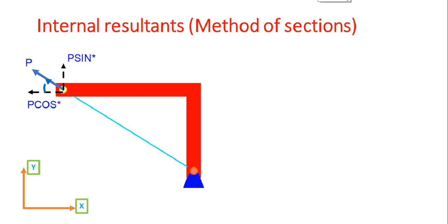Now, a pin joint can resist movement, so the first thing to investigate is whether the applied loading produces movement at the end point or not. From our previous lecture we know that a pin joint will constrain translational motion, so there will be reactions in the horizontal and vertical directions. Let's call these reactions Rx and Ry and take them as positive, along the positive x-axis and along the positive y-axis. Now we'll apply the equilibrium conditions to find the reactions and verify that the moment about the pin joint is 0.